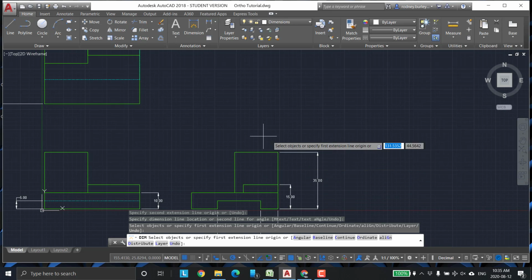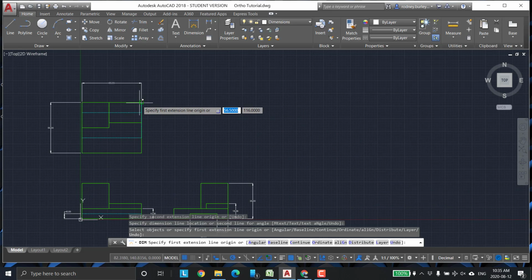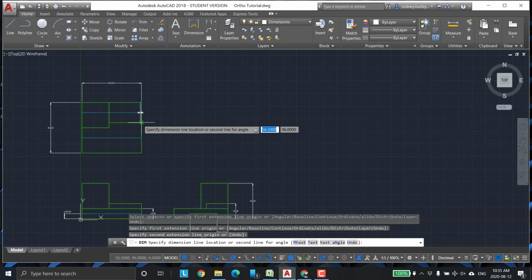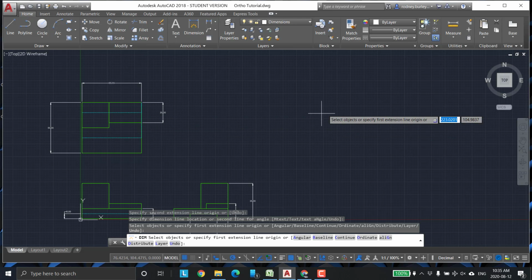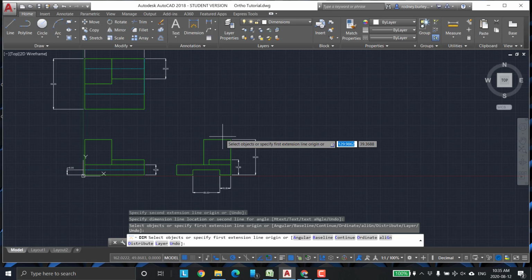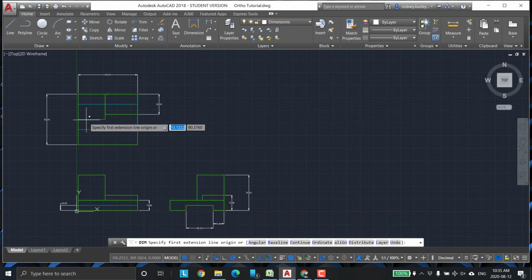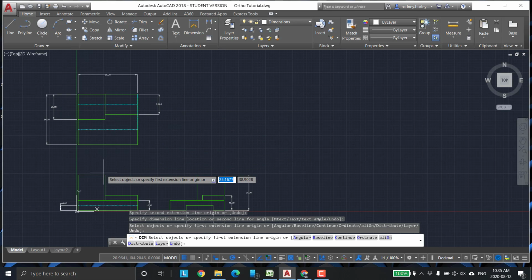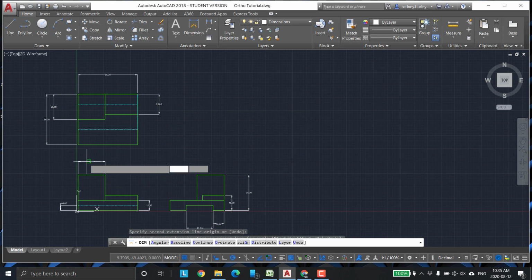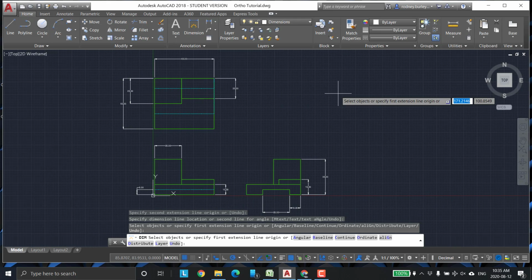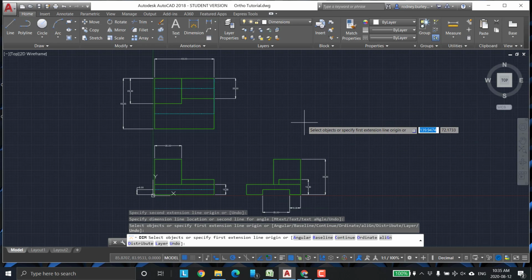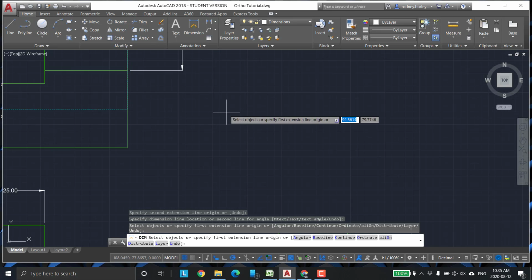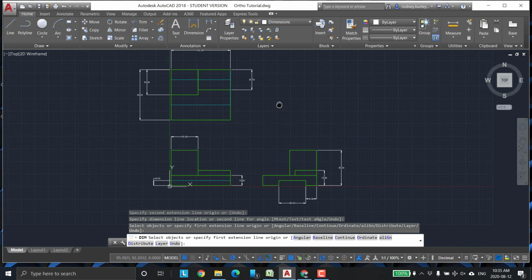So I could come over here and go, okay, this is my B datum on this side, so I could go from there to there and set that dimension, right? And I need to know the height. This is a square 25 by 25, so I could do this square here to here, maybe, and then this dimension across here is 25. So you continue that, again, trying to keep your drawing as simple as possible. You could make the numbers a little bit bigger if you wanted to. I'm having a hard time seeing them right now. I have to zoom in to see them, but I need glasses, so there's a different thing there altogether.